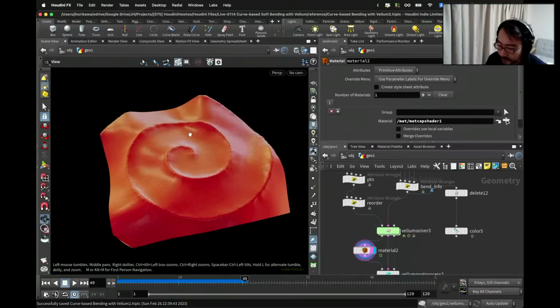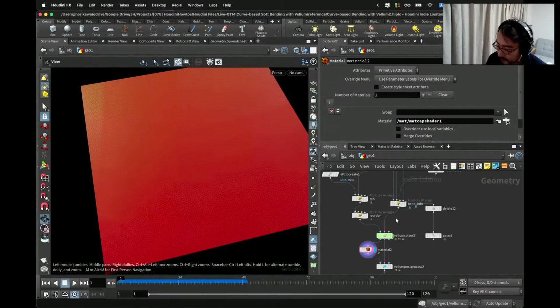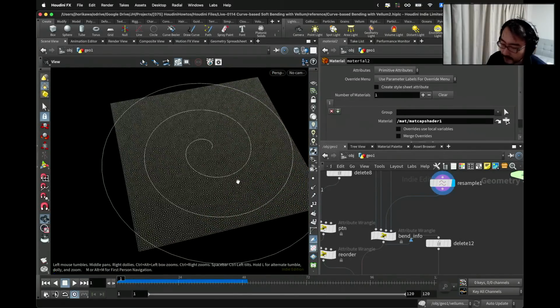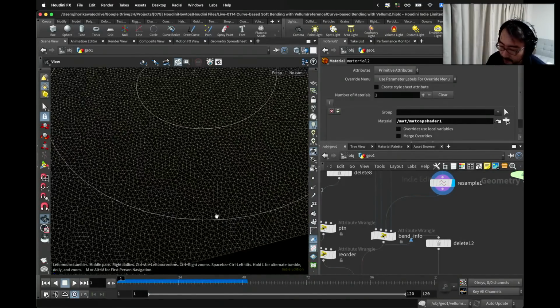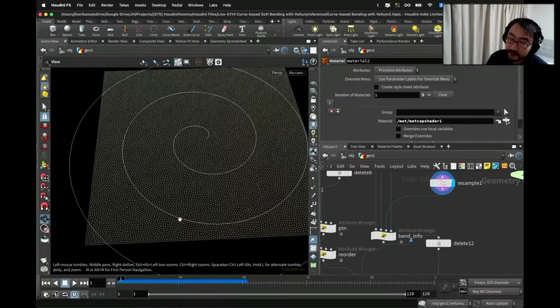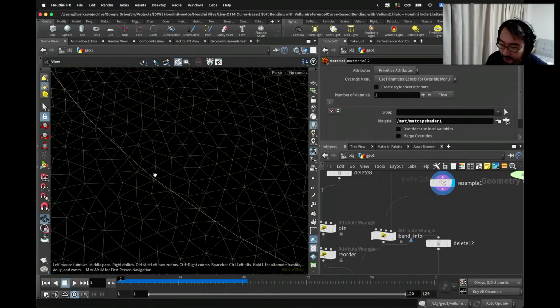But for this one that I'm going to show you today, you don't really need to cut or modify your mesh at all based on your input curve. You just need to calculate the bending angle based on the curve information for each bending constraint for Vellum.